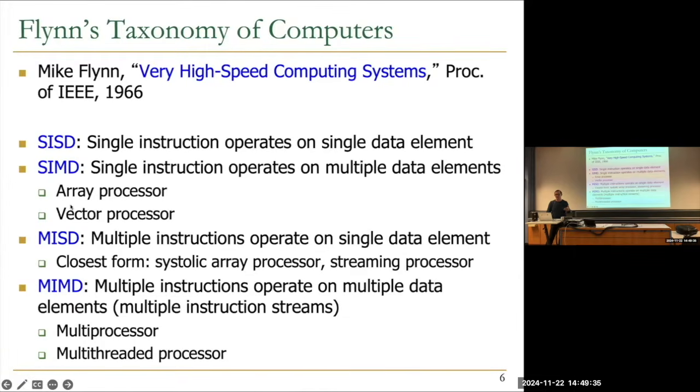Essentially, the benefit is you unleash a lot of work, but a different way of looking at unleashing a lot of work with a single instruction is that you reduce the overhead of control. Now, what does this mean? If you have single instruction, single data, every instruction specifies a little amount of work. So the amount of control that each instruction goes through is a big part of the overhead. Really the computation is executing on lots of data. But you need to fetch the instruction, decode the instruction, rename the instruction. A lot of processing needs to be done on that instruction so that you can do some work on two pieces of data.